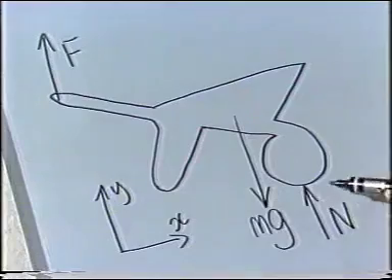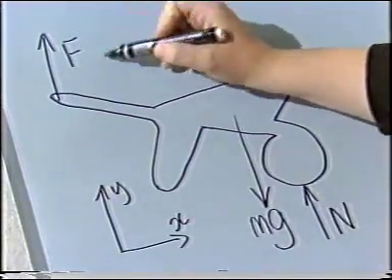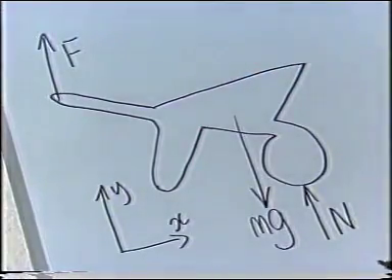So, I've drawn a profile of the body with no internal details. I've marked the forces I do know, taking care with their lines of action and their points of application, and I've assigned symbols to represent the forces that I don't know. Since the body is static, I know that no net forces or moments act on it, so I can now apply conditions for the equilibrium of the body.